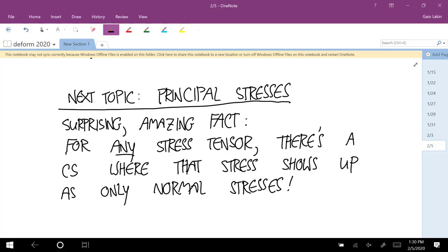For a material, that means, load some body. Okay, so if I press down on this, I'm creating stresses over here by the hinges, and we could measure those stresses and we get some shears and some normals. And then we could convert it to a coordinate system where if we had taken those measurements in that coordinate system to start with, all we would have is normal stresses.